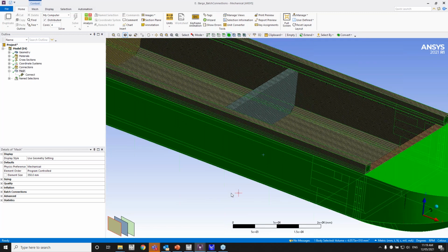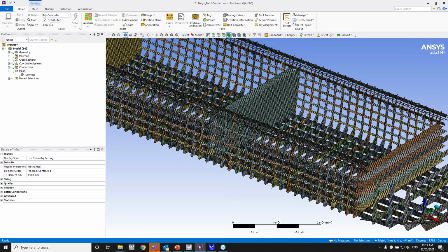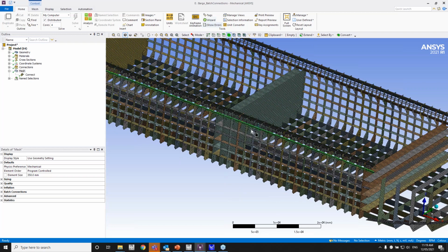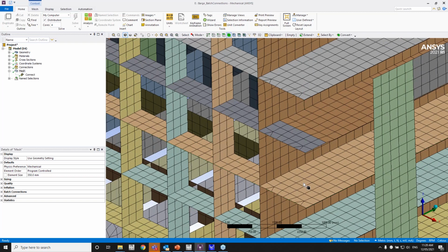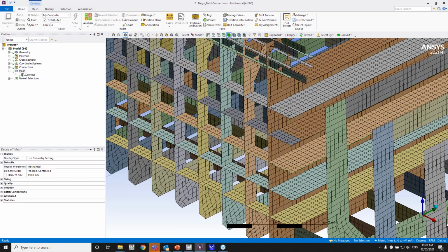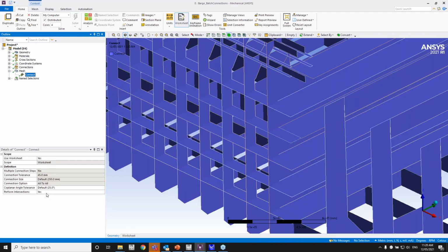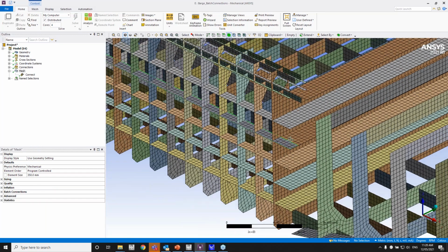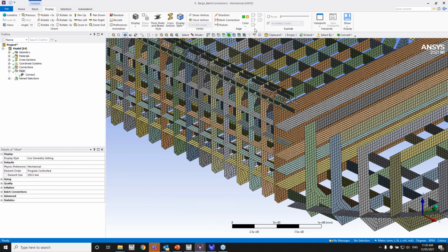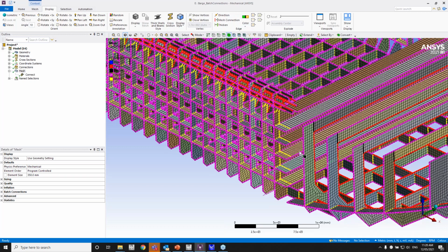Let me go ahead and hide the external hull surface. As you can see, there's a lot of small edges, faces, intersections, and so on. I should have touched on this before: you can perform intersections as well. I've talked about it under the features list, so I had that turned on here. As you can see, there's a lot of faces. Let me turn on the connectivity to check for connectivity as well. It's just going to take some time because it's a fairly large model.